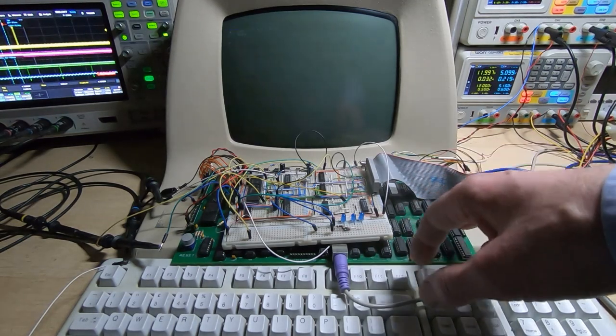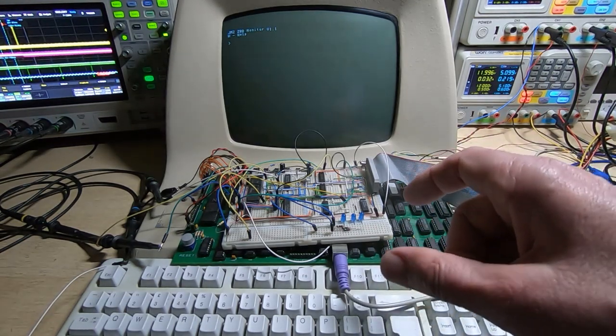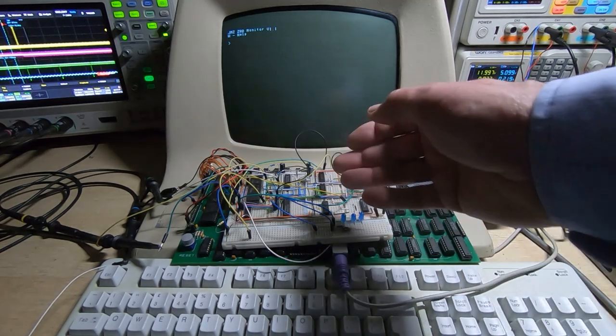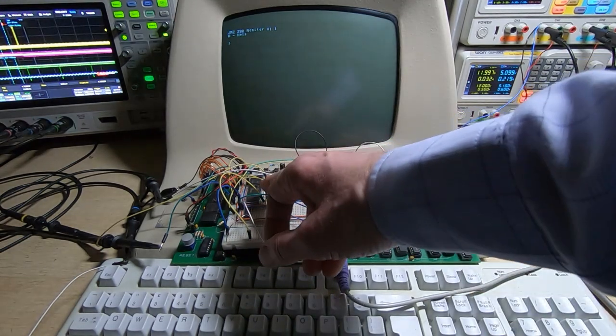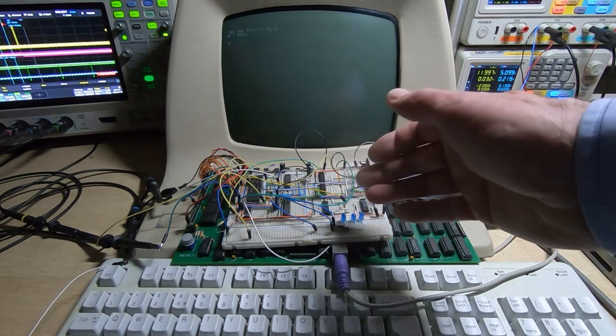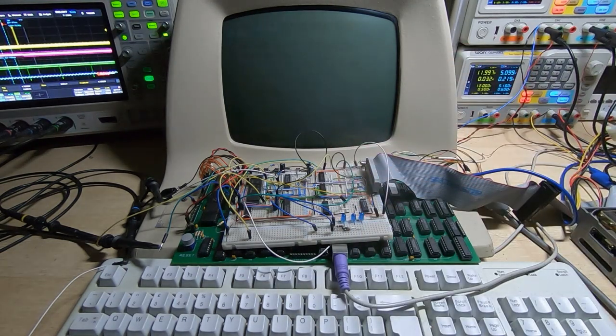It's quite difficult at the moment because I'm still running the board at 2.5 megahertz, and that's really pushing the limits as to being able to read a floppy disk in code rather than using DMA. But effectively, we write bytes directly to the floppy drive controller. It then writes all the bytes to the disk, and we have to make sure that we're writing the correct bytes, as I've just been talking about, when we format the disk.